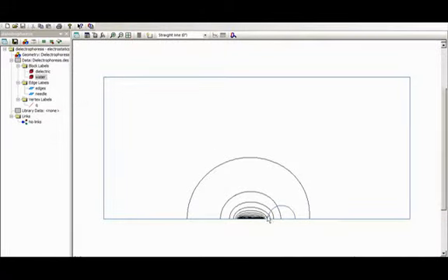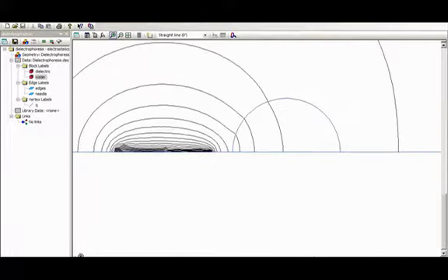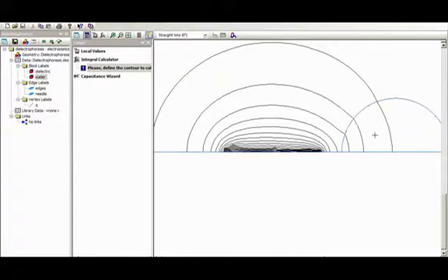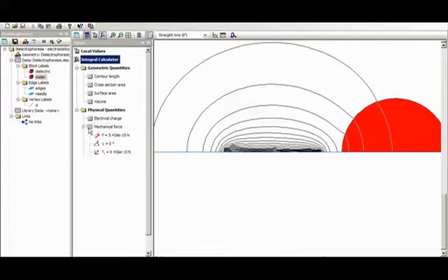Okay. So the needle is above the dielectric sphere. These are the equipotentials due to the needle. And what I want to calculate is the force that's acting on the sphere. And to do that, I will surround it by a contour. I've gone to my contour tool, and I can simply come around here. Okay. And then I can look at the integral values. Okay, and this region is highlighted here, so I'm looking at volume integral.